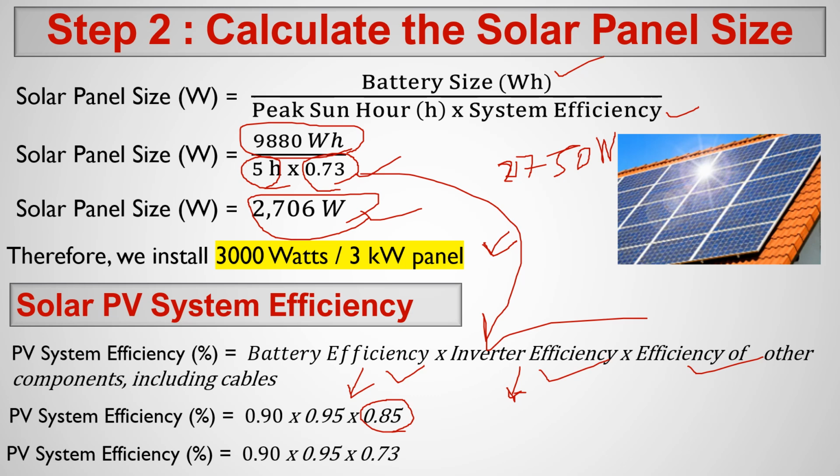Because of the particles, solar panels will not produce a lot of the rated power because of the shading issues, particles on the panels. So all because of this reason we go for a little higher value. So now we found the panel size as 3 kilowatt panel.